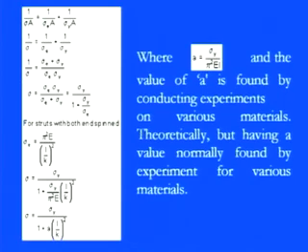So in the Rankine formula, we have sigma, which is the final equivalent buckling stress, equal to sigma y divided by 1 plus sigma y by sigma E. These are the crucial things in this case. Now for the strut with both ends pinned, we know that sigma E is equal to pi square EI by L square.